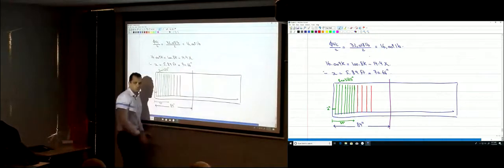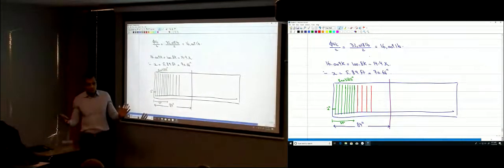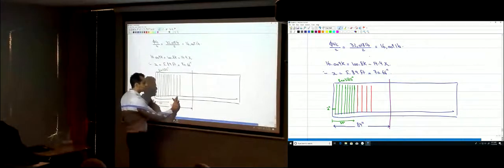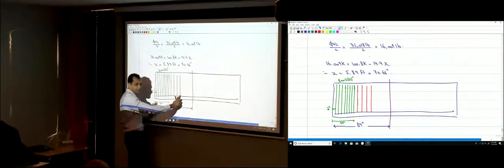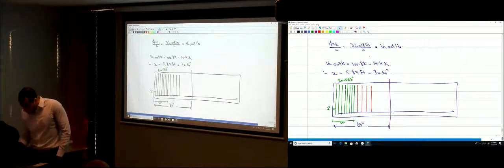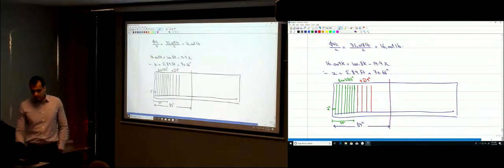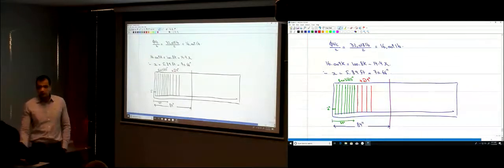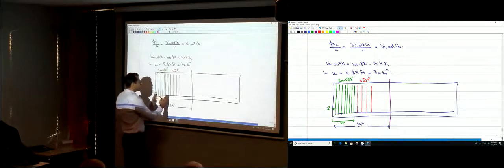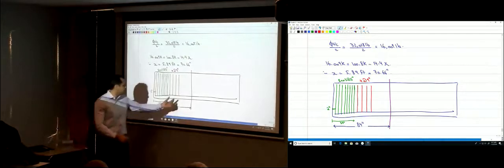At 70 inches, at the distance of 70 inches, I don't need to provide stirrups anymore. Okay? So I provided till 73, because if I stop here, this is not 70. This is what? 64. So I need to provide that extra one. Okay? So right now, what I had here is 4 stirrups at 9 inches. And then no stirrups. Okay? So I put 8 stirrups at 5 inches spacing, and then 4 stirrups at 9 inches spacing. And that's it. And that middle part here is going to be empty.